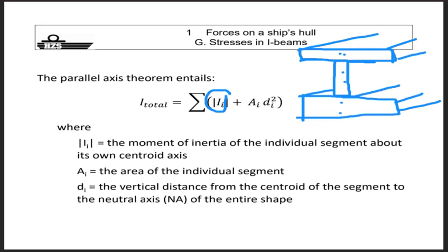Yeah, because why around the neutral axis? Because we know that around the neutral axis, your stress evolution goes through 0 at the neutral axis. Suppose it's perfectly symmetrical, it will be mid-height only when it's perfectly symmetrical in area and volume distribution. It will be perfectly in the middle.